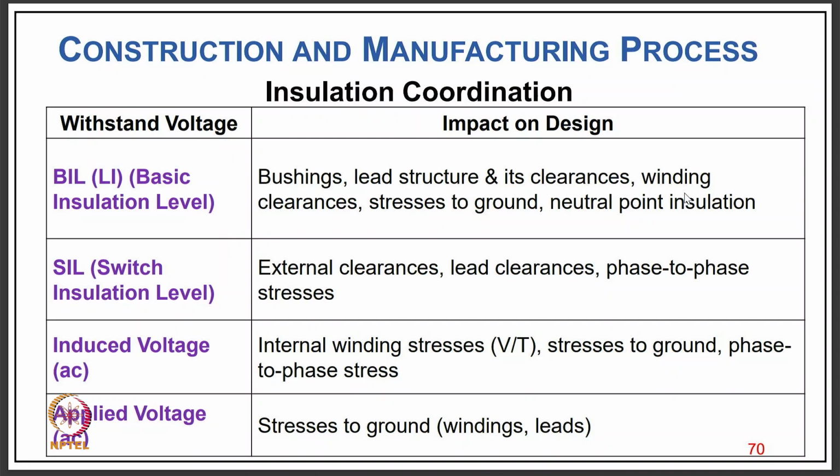Then we have in SIL, the switching insulation level, the external clearances, lead clearances and phase to phase stresses. Then we have induced voltage, with internal winding stresses, stress to ground and phase to phase stress, and applied voltage, that is stress to ground, winding and leads.